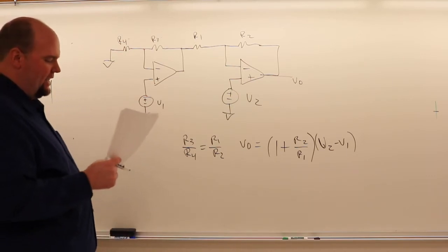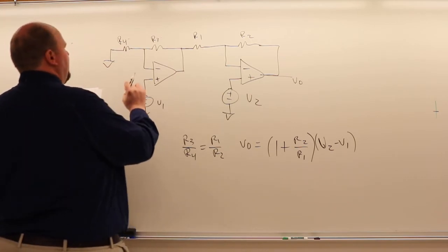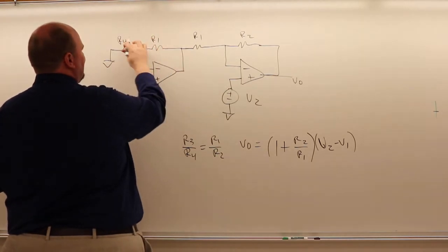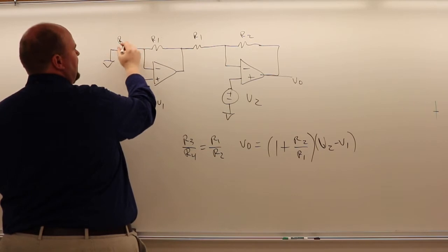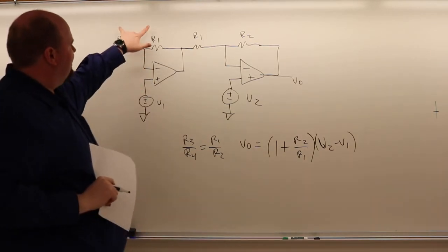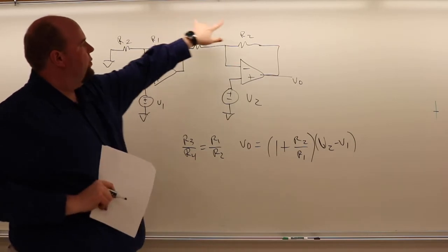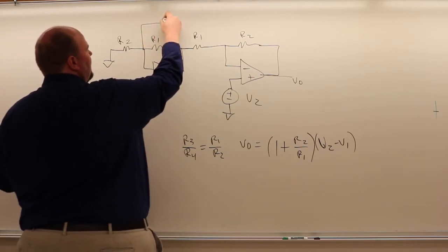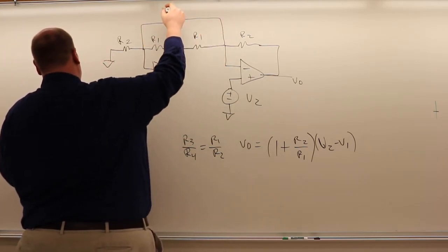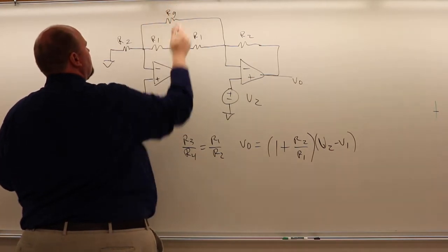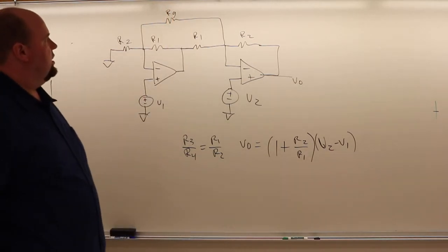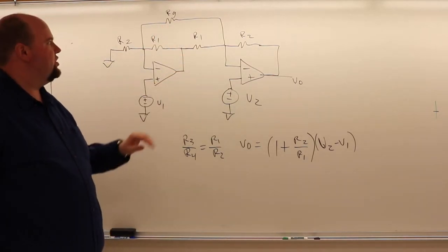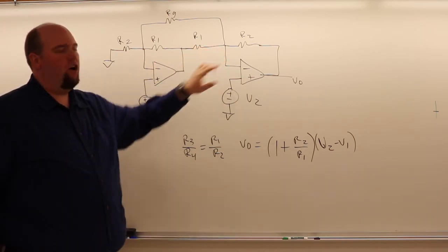If we want to add gain, we do have to keep these exactly the same. So internally, these resistor values would have to stay the same. So we'd have R2, R1, R1, R2. Keep in mind it's the same but flipped here. But then we would add an extra resistance here. By putting this resistance here, it allows us to maintain our ratios as we did before, but still change this equivalent ratio R1, R2.